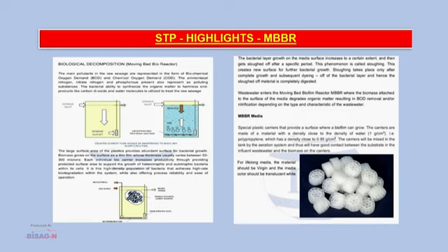Wastewater enters the moving bed biofilm reactor, MBBR, where the biomass attached to the surface of the media degrades organic matter, resulting in BOD removal and or nitrification depending on the type and characteristic of the wastewater.